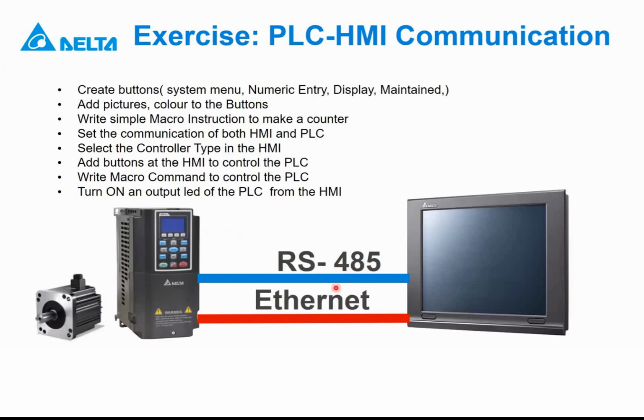You can connect the HMI directly to the incubator and control it. But if the incubator has another controller like a PLC, you connect the HMI to the PLC, and the PLC reads the temperature sensor of the incubator and feeds it back to the HMI. So from the HMI, you can start the incubator, set its temperature, monitor and see how the eggs are doing, and do different kinds of things. Also, depending on the types of sensors you have on the incubator, you can get the feedback of those sensors from the HMI. Yes, it's possible.